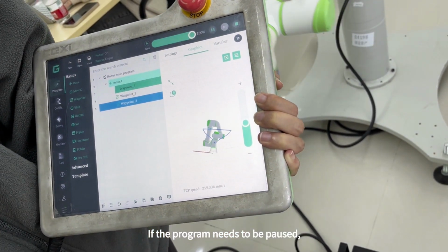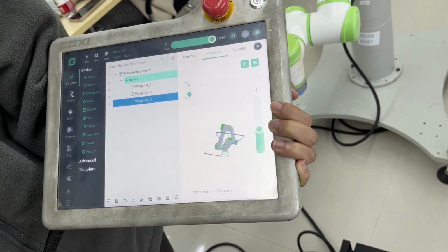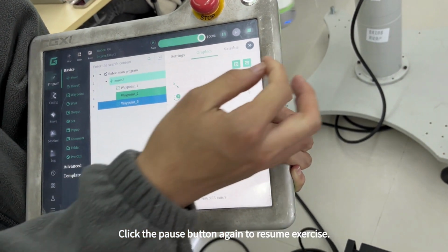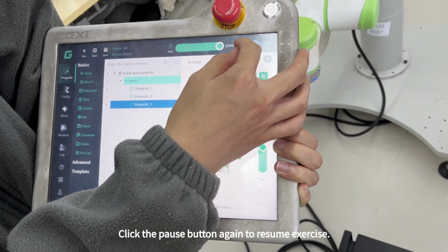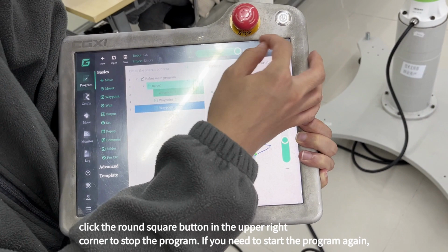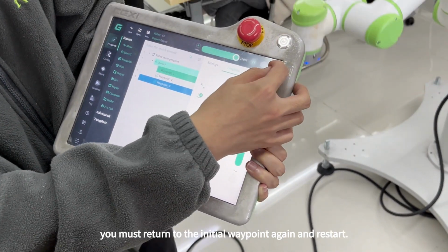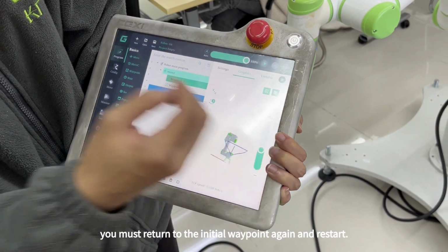If the program needs to be paused, it can be paused immediately at any waypoint location. Click the Pause button again to resume movement. If you need to stop, click the round square button in the upper right corner to stop the program. If you need to start the program, you must return to the initial waypoint again and restart.